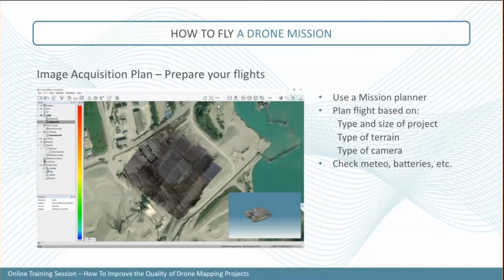And also, if you're using ground control points, make sure that they are well distributed over your project of interest, because this way you'll make sure that the overall accuracy is well distributed over the block. We've seen some projects before where, on a project of 800 to 900 images, we had 4 ground control points, but they were only on one side of the project. So make sure that those ground control points are all distributed throughout the AOI, so you have good accuracy over all your project.